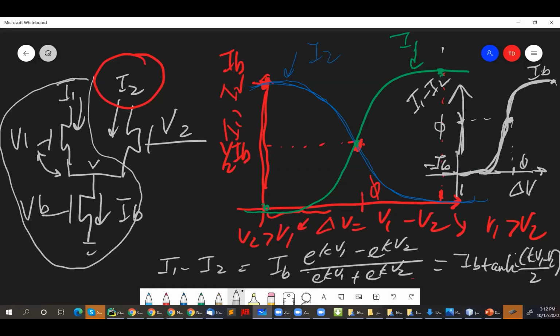Of course, it's a range of VGS values for the transistors in subthreshold, but let's just say it's 0.4 volts. Just pick one value only. So I've got three voltages that I can drive: V1, V2, and VB. Which of the three voltages should I set to this 0.4 volt VGS value?